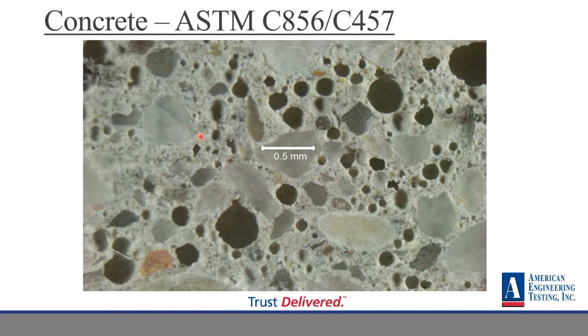I haven't seen anybody report, and I've read a couple of technical articles, that expanded shale lightweight aggregate does not cause bulk alkali-silica reactivity in concrete. I think it might have to do with it counteracting itself, because there's enough glass in enough of the aggregate used that it might not produce bulk reaction.